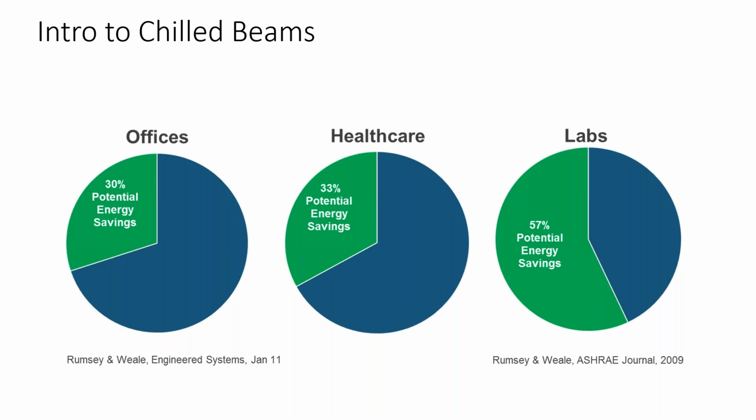Now with healthcare specifically, in acute care patient rooms, as approved by ASHRAE 170 standard for healthcare applications, the total airflow can be with a chilled beam combined with the 2 air change minimum ventilation requirement and the other 2 to 4 air changes induced at the chilled beam within the space can actually combine to get your total air changes for the room. So there could be quite a significant energy savings in BTUs per square foot by going that route with a chilled beam in patient rooms.